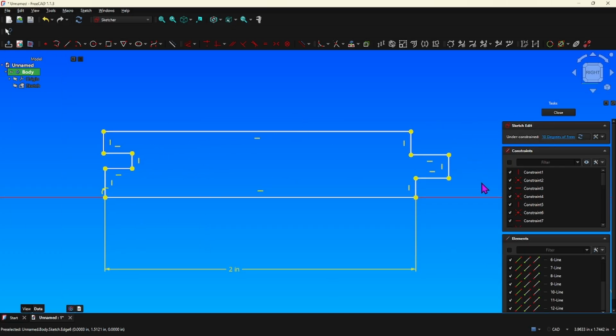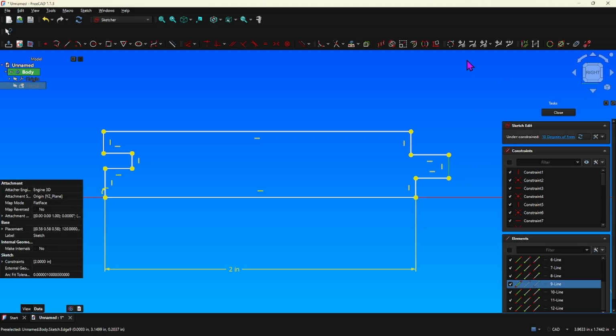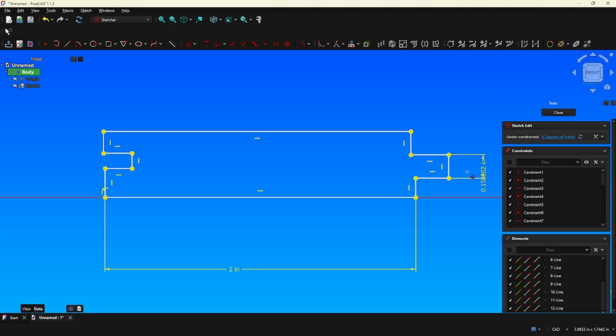So he was using 3/16 as a division, but that would put us at 9/16, which is actually over a half of an inch. So what I'm going to do, I'll just make this tongue here 3/16.